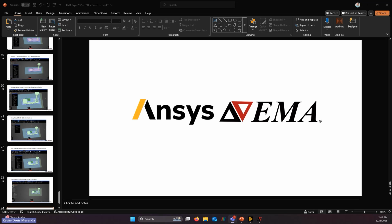I think that's pretty much the only benefit. You remove a lot of fidelity that you may have in your 3D CAD model. There may be some features that will add some asymmetry in the discharge phenomena that you want to be able to capture. You may have some B fields that may be asymmetric, things like that. So I think going 3D is what the solver was designed for, and solving this efficiently in 3D is ultimately the goal.